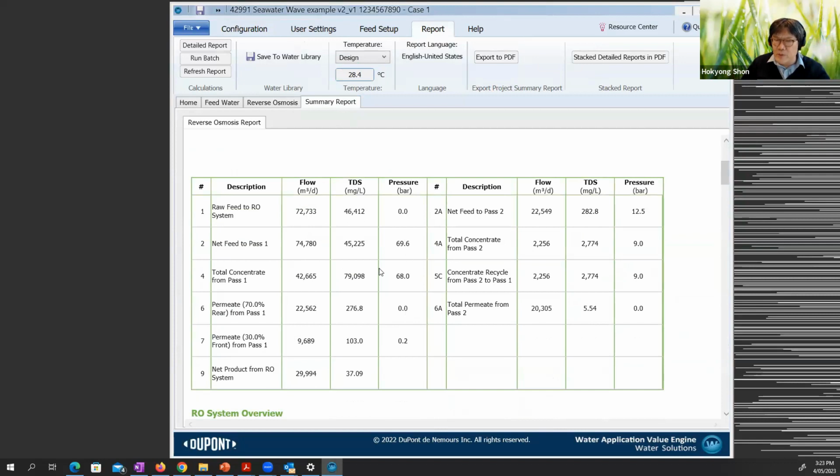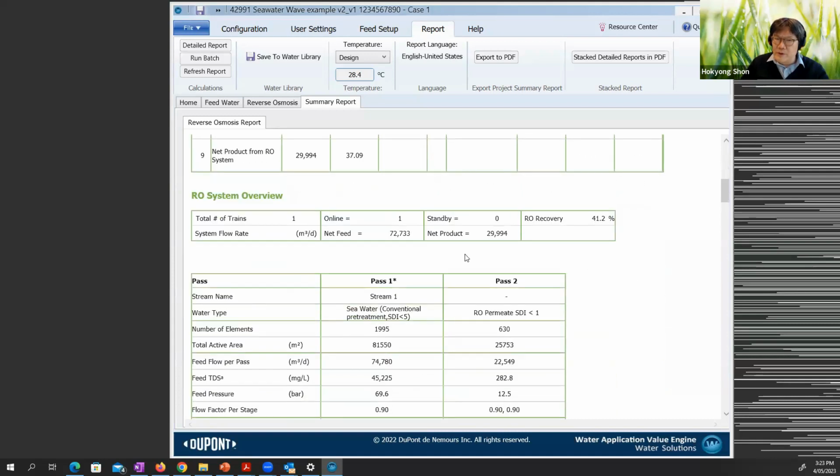You don't set that up, because it is automatically set by your computer software, because your membrane, your recovery rate, and your flux will calculate this much net pressure. Then based on that, you can have a back pressure, you can consider a delta P and pre-stage additional pressure, and then you will have a little bit better flow.